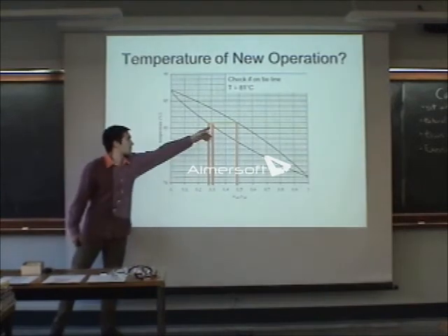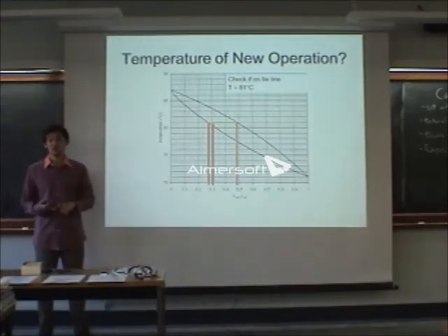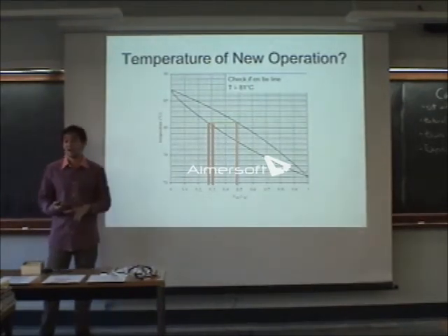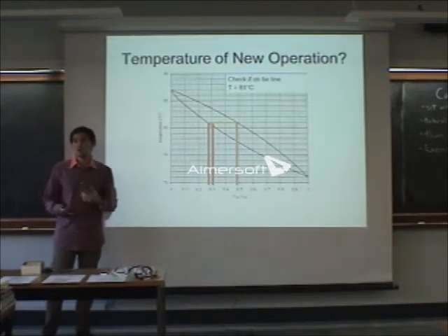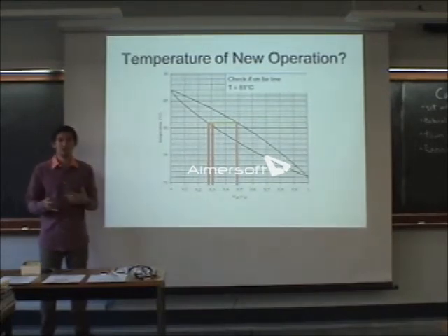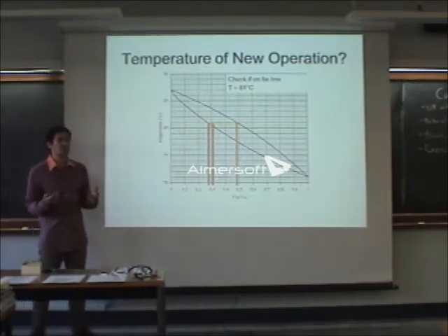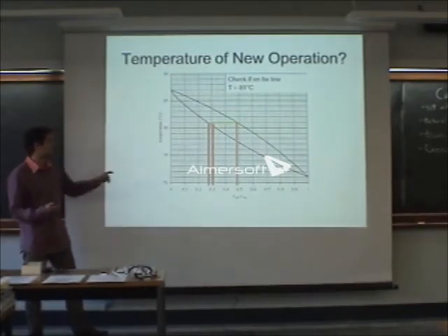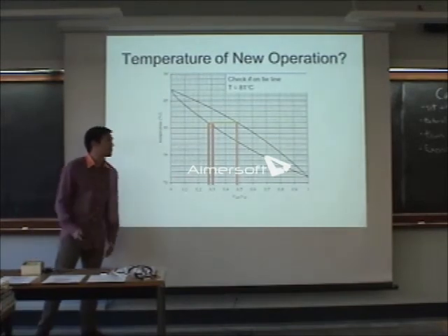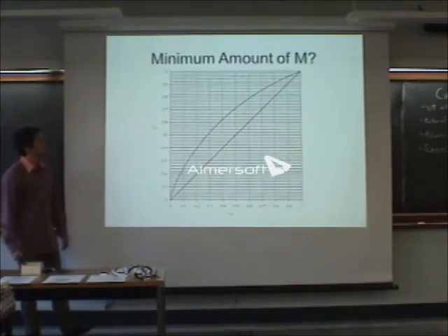And those are the conditions that we just changed. We just adjusted L over V for both the rectifying and the stripping sections. So really there are many solutions to this problem. It's really just guessing and checking, changing the slopes and seeing where's the fifth stage, where's the composition of the fifth stage, and whether it meets the requirement that 0.3 fits within the vapor-liquid composition.